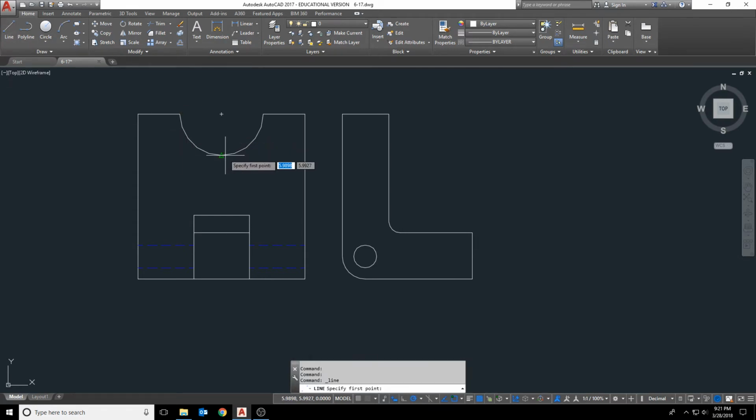And I want to project the quadrant of this line over to this view. Because we're not actually cutting anything going through here in our section view, I'm going to draw just a line down through here and put some lines making an arrowhead on it to just show where my section view actually is. And then I'm going to break this line because a solid line going through the whole view doesn't really look appealing to me.